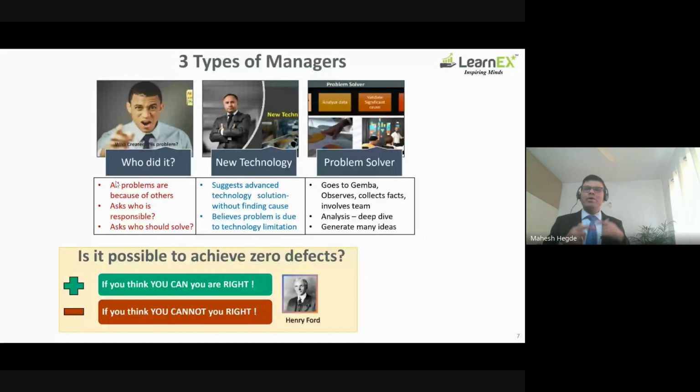Step 1, step 2, we have a counting. You arrange the data of the best and worst from smallest to largest and look at the end count. There's a method, so I applied the method. Then I told him, out of these 84, these are the 4 parameters which are significant. You change this parameter from here to here, and that one from here to here, and your problem will be solved. Then how do you say that? I said, I'm not saying, your parts are saying, your data is saying. Why don't you experiment? So he experimented. With the new or changed spec, they sent about 200 tires, and no tire failed. Then they made a design change, and that gave 1.3 crore saving. It was the biggest success in terms of warranty reduction.